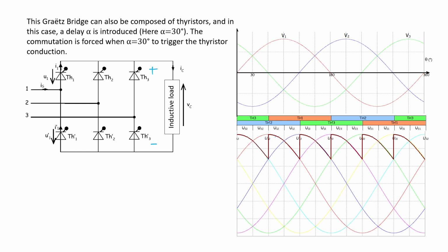So why do we want that? Because if we use diode, we only have a fixed average voltage of VH. But in some cases, especially when you build a power supply, sometimes you want to change the voltage to be this amount, that amount, right? So thyristor would be useful in that case.